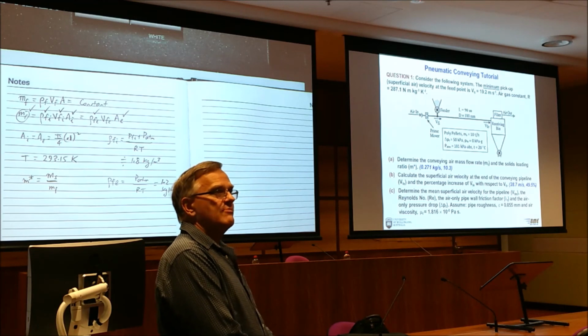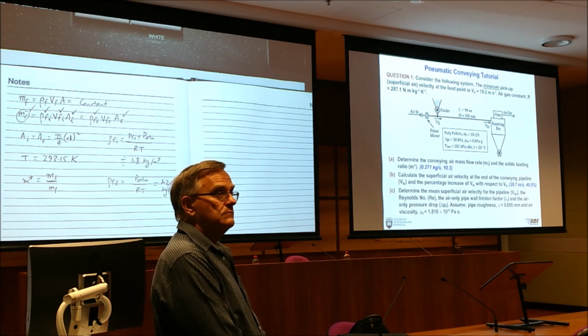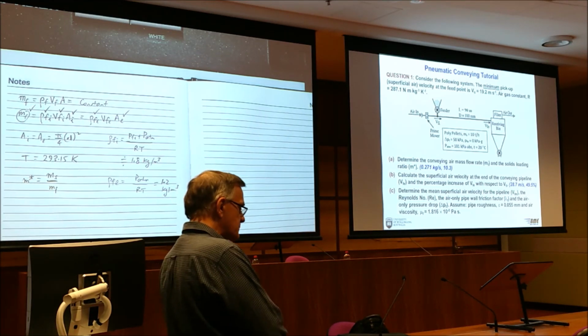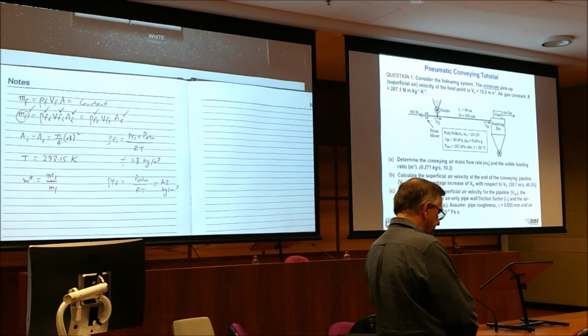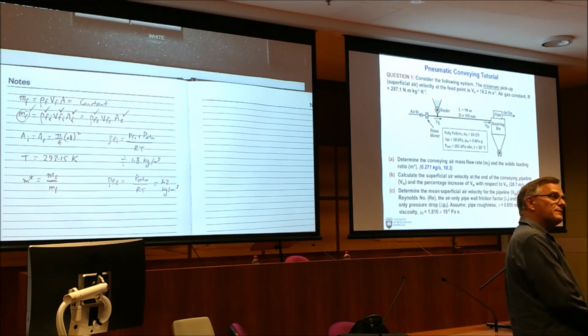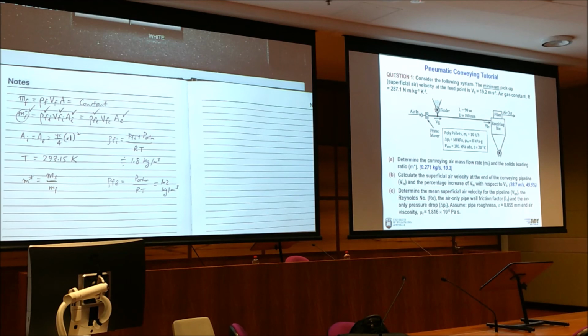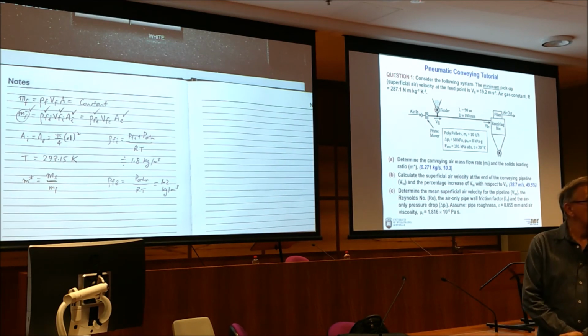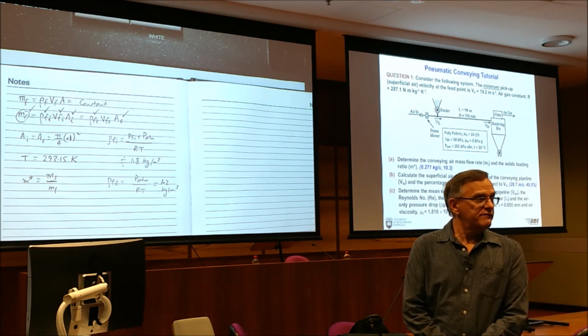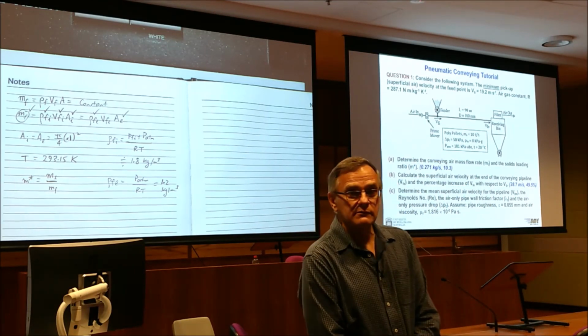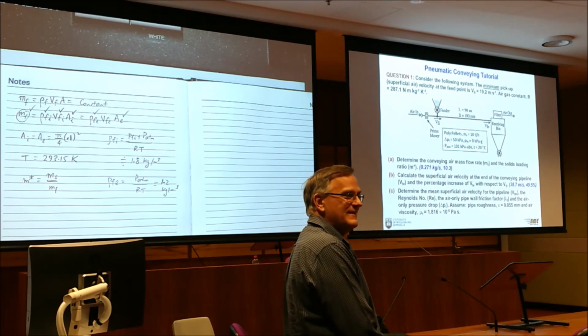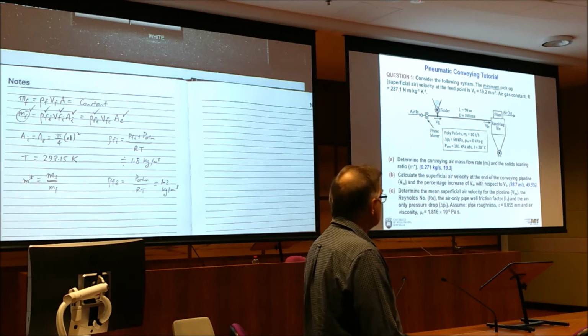That's what most people will do. They'll say VFM equals VFI plus VFE divided by 2. Unfortunately, that's wrong. Because what you're doing, you're naturally assuming that the velocity increases linearly through the pipeline, and it doesn't. Rho v is constant. That's a hyperbolic function, I think. Is that the right mathematical term? I can't remember the mathematics. Anyhow, rho v is constant. It's not linear, right?